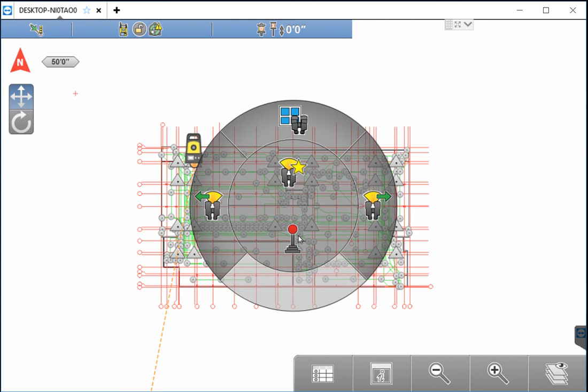The binoculars with the star in the middle of the circle will perform what's called a power search. This is when the total station automatically begins turning in a complete circle until it either finds the prism or completes its circle. I rarely use this function as it is more random, and I would rather control the total station in the direction I know I need to turn.